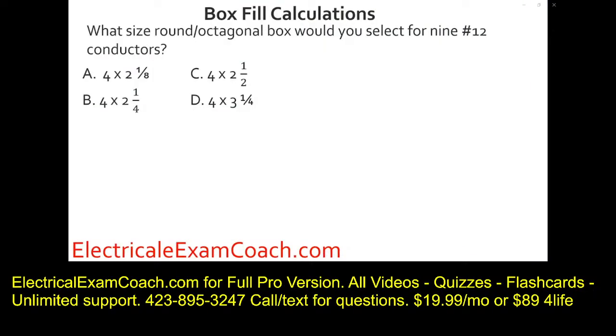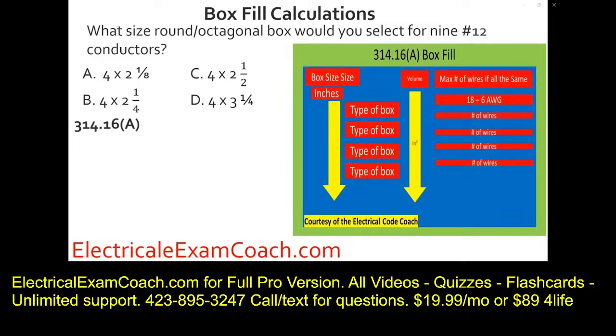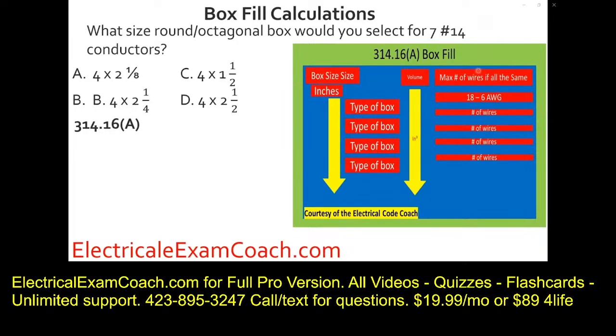What size round octagonal box would you select for 9 number 12 conductors? For this one, we're going to be using Table 314.16(A). We're going to start here and we're going to find our gauge of wire. Then we're going to come down here on the right-hand side and find our gauge wire. Then we're going to come down and find a box that fits it, and be sure when we cross over that we stay in the right category of box, and we're going to select C.